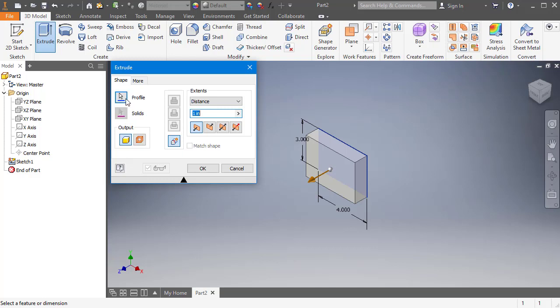The first thing that we're going to do is we're going to use this profile. The profile is our sketch one and we had our sketch one selected already. So the output here, there's two different options. One is solid, one is a surface. In this case, we are always going to be wanting to do a solid at this point. Surfaces are more complicated. Later on, you can do that later. But for now, just know that we're going to do a solid output. These center options will become more active as we get more and more features there. In this case, we only have one sketch and we don't have any features in our part yet. So it's going to make a new solid down here. So that's going to be kind of our new solid.